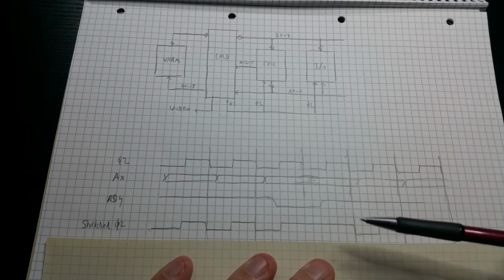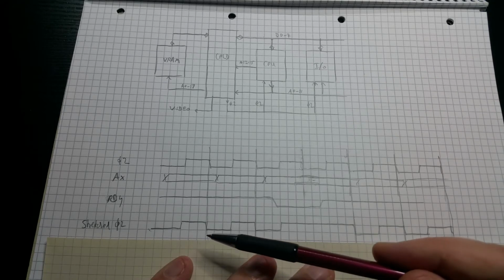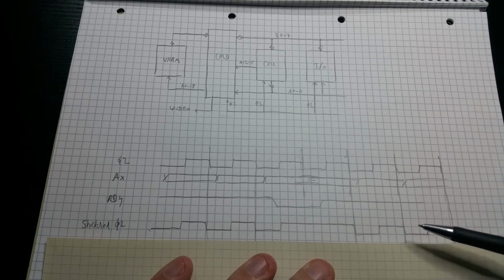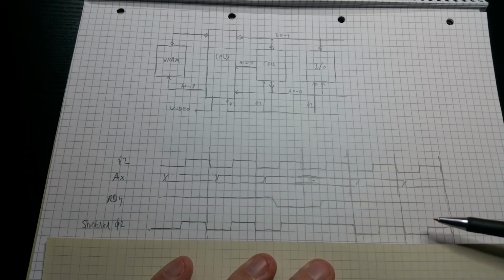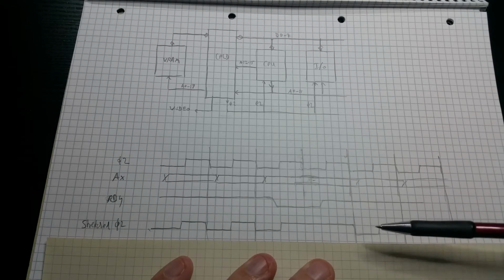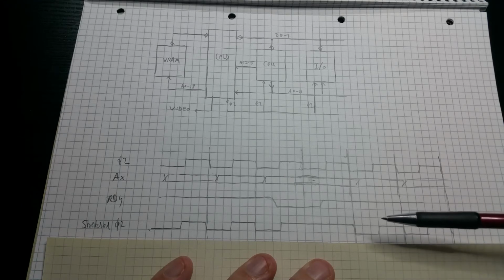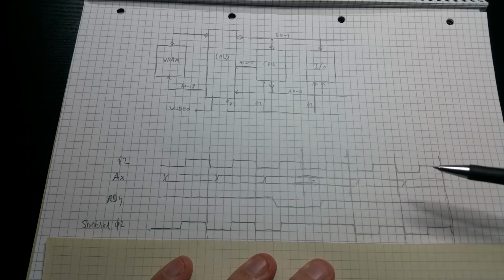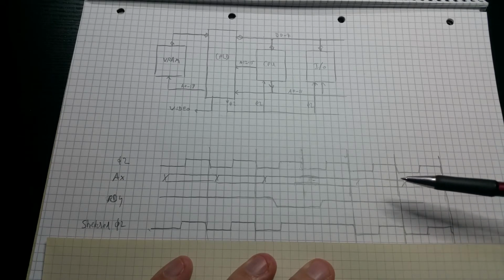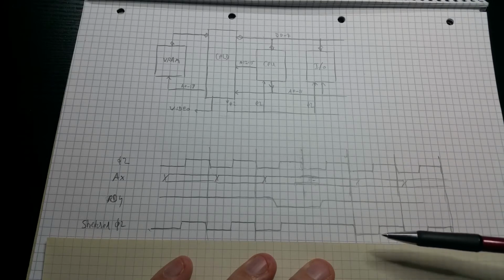which has a 1 megahertz clock, phi 2, and the system timer here should be running at 1 megahertz. So what I'm doing here is I am actually stretching the clock for basically 7 cycles, and I only let the eighth cycle do the actual memory transfer. So I have a base system clock of 8 megahertz. That's for the composite video. VGA video is a little bit more complicated, but it's not important here.